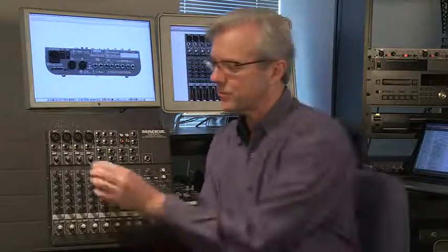The parametric, a really good parametric, which this one is not a full parametric, I would have a separate control over the center frequency of this. This one is set to 80 hertz, but in a good parametric, I would have another knob which would allow me to move that center frequency up to 100 or wherever I want in that range and really specify exactly where the frequency center point is I want.